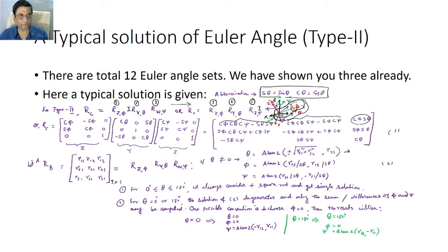If you consider that this is an aircraft, then with respect to the aircraft A, B is the runway. So the orientation of the runway B with respect to the aircraft is given. Now the aircraft needs to plan what theta, phi, psi will be, so that it can actually take that orientation. So this is equal to this, with this equal sign.